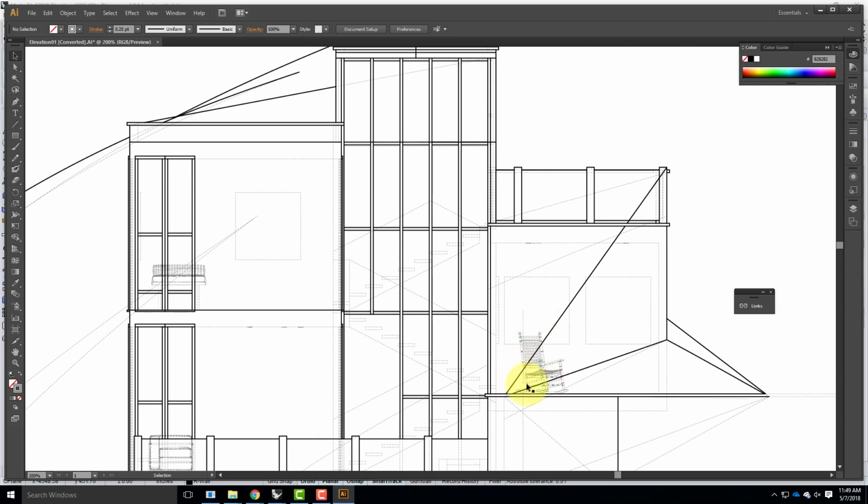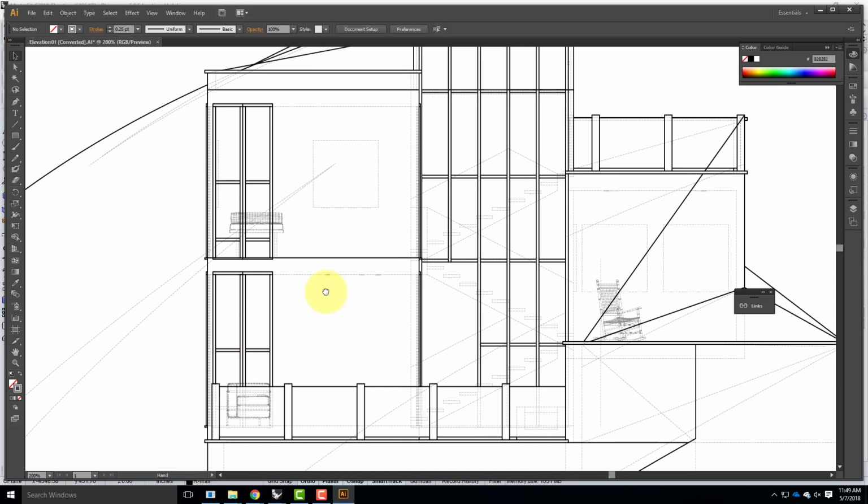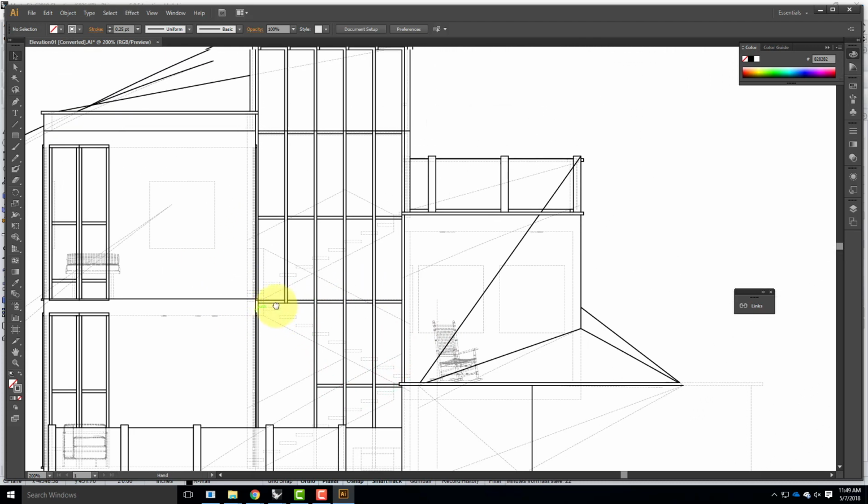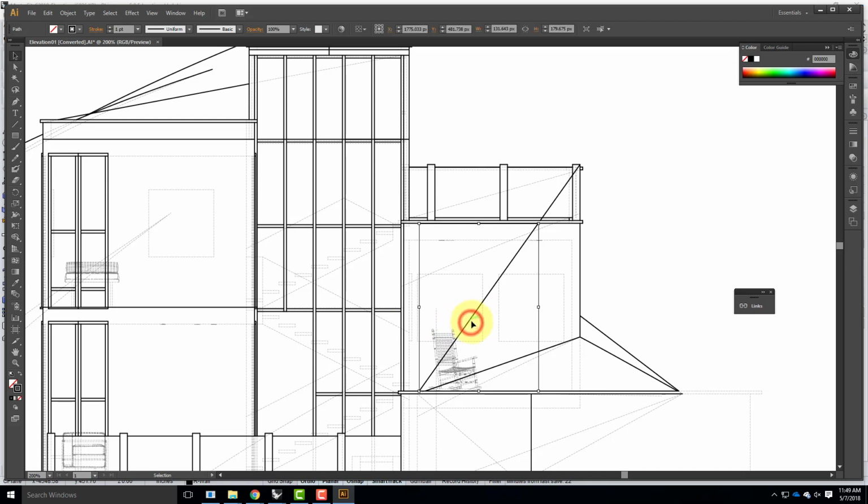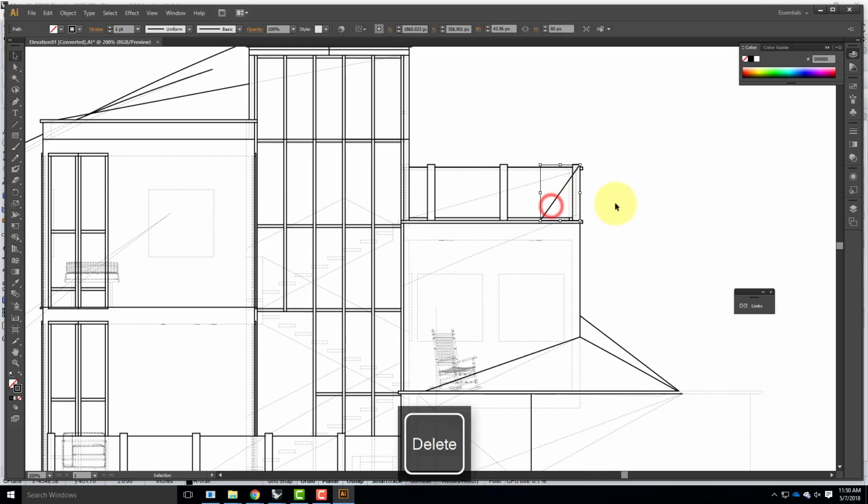Do I really need the hidden lines of the rocking chair? Probably not. But I did the export with those on. If you have trouble with the Make 2D, just go ahead and turn off any of these objects or delete the blocks before you do it. There's always some cleanup when we go to do this. This line here, this diagonal line, I should have turned off beforehand. That was used when I punched through the ground. So I'm just going to select it using the black arrow here, and I'll press the delete key. And we'll clean that part up. Likewise, this little line should go away.